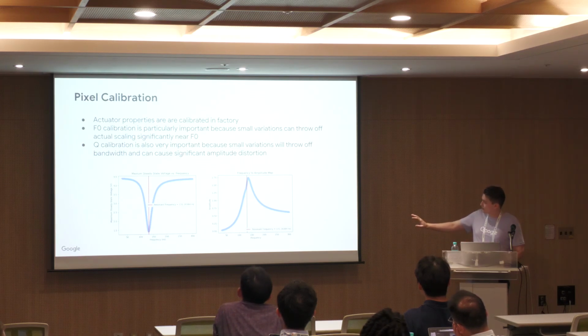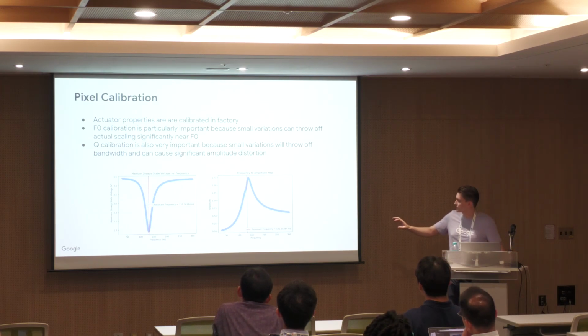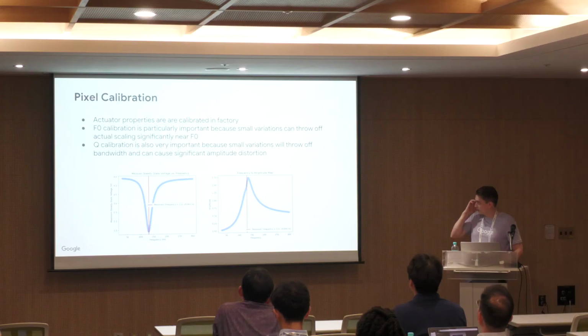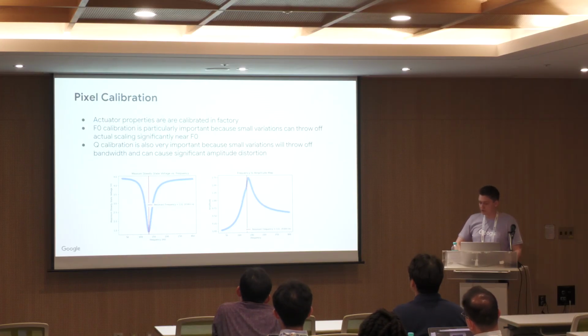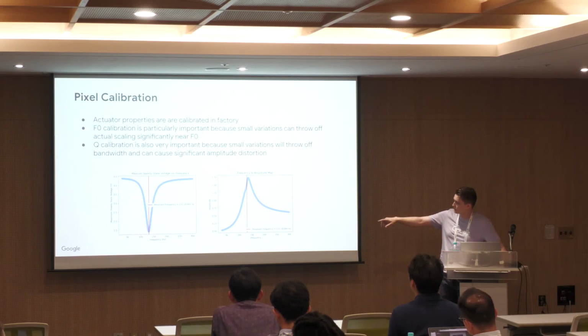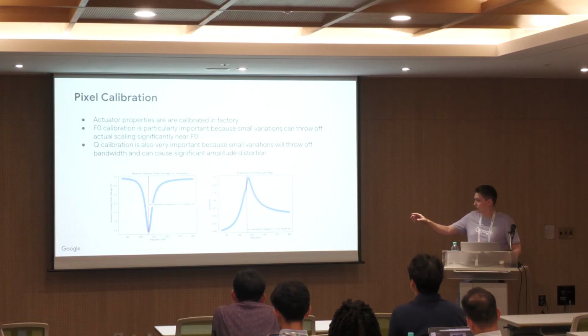As an example, these are some plots we generated while investigating the frequency to output acceleration map. On the left, you see a maximum steady state voltage curve versus the frequency. This is a calibrated curve because the resonant frequency is aligned with the minimum voltage, or the minimum maximum voltage, I guess.